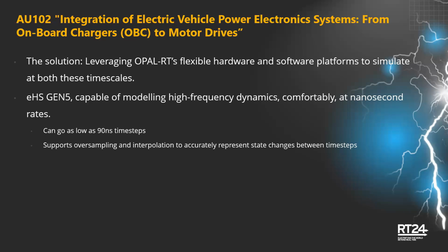So in essence, we are going to show off both an FPGA simulating these complex fast-switching dynamics, and also the CPU simulating the slower dynamics, namely some of the battery stuff, because the battery here is modeled in the CPU, whereas the actual inverters and onboard chargers are inside the FPGA.